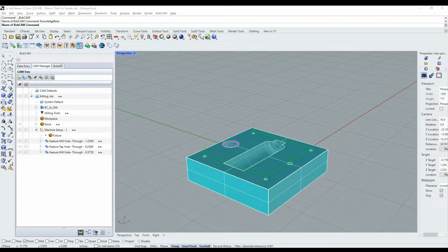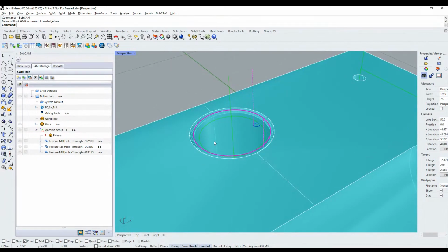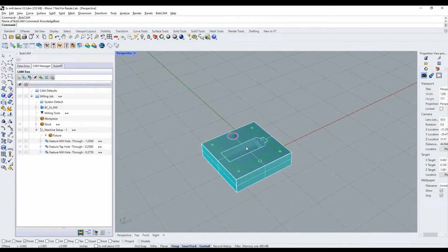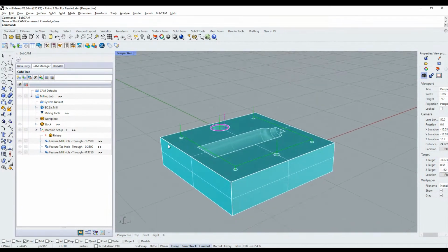Once you click on knowledge base, you can tell the software, for example here, the chamfer. If the hole has a chamfer and is less than .625, it'll do a chamfer drill by default. And if the chamfer is larger than .625, it'll do a chamfer mill by default. So those kinds of settings, depending on the hole sizes, we have templates or default settings for different hole parameters.